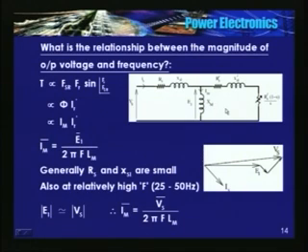It is known that the magnetic circuit used in machines or in a transformer is generally operated at the knee point. The knee point is where saturation begins to start. Till the knee point the magnetic circuit is linear, and above the knee point it starts saturating and becomes non-linear.